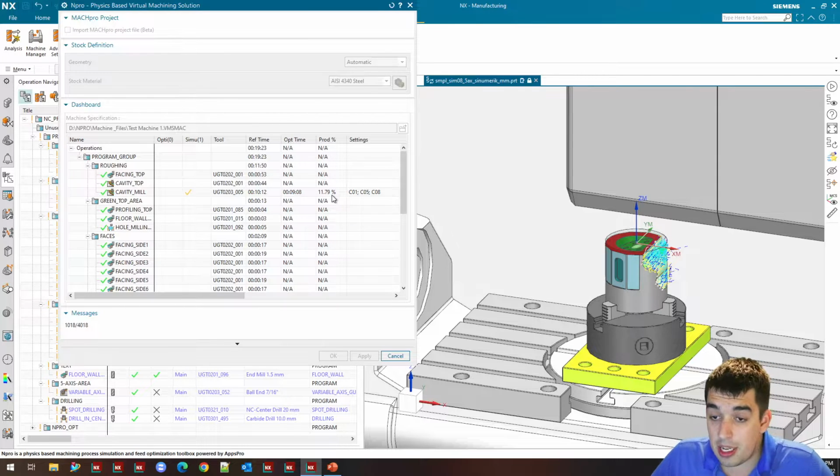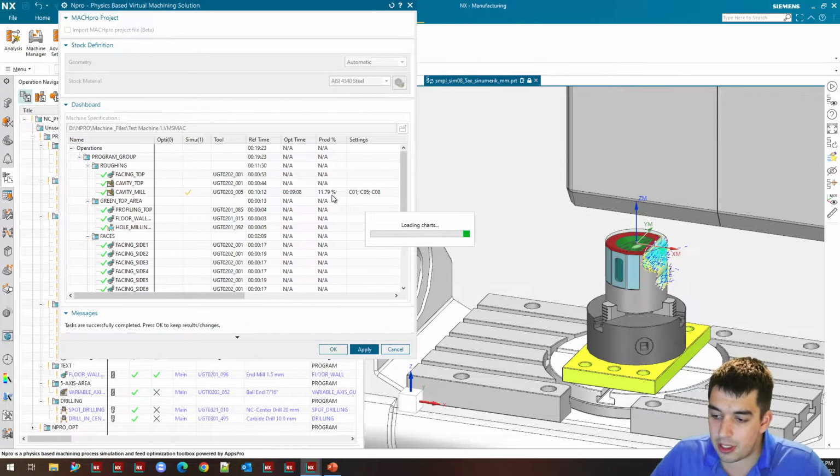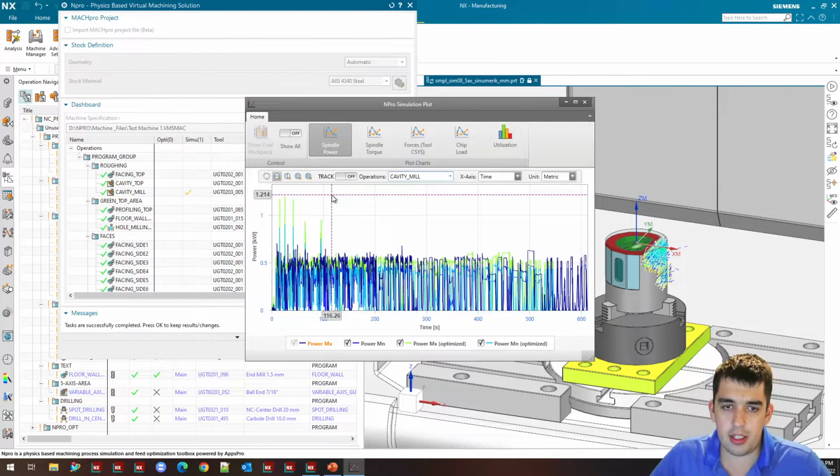So this to me is pretty good. I mean, we don't expect to see any significant increase in tool wear because again, we're not applying more pressure to the tool. We're not pushing the tool beyond its recommended chip thickness. So everything is going to stay pretty stable. This is effectively as close as you're going to be able to get to free productivity. It just costs us a couple minutes here to compute and generate these tool paths.